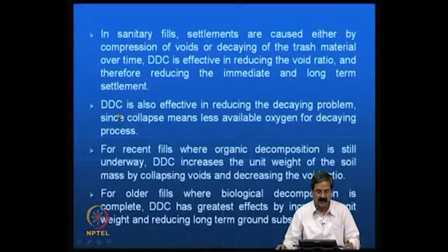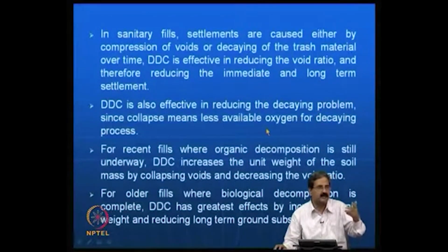And a very important point is that, since it reduces the void ratio, dynamic compaction is also effective in reducing the decaying problem, because biodegradation activity occurs because of the availability of oxygen.